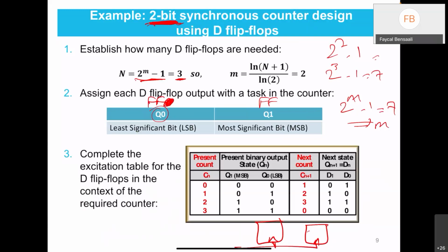Usually we start from 0 when we talk about bit 0, bit 1. So flip-flop 0 gives us Q0, which represents the first bit of the output, the least significant bit. So we will have Q1 Q0 going 00, 01, 10, 11. The first flip-flop gives me the first bit, the second flip-flop gives me the second bit, and so on.